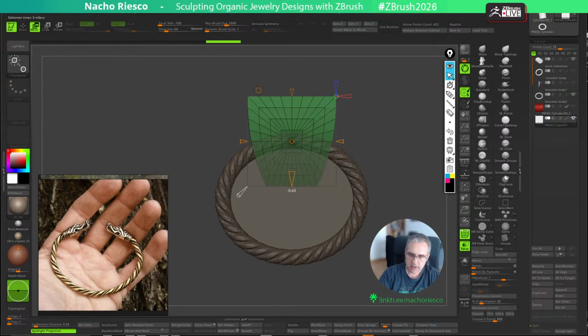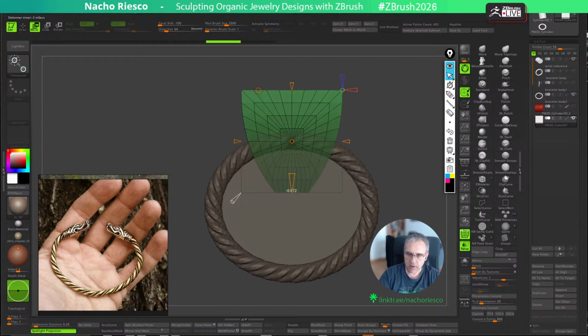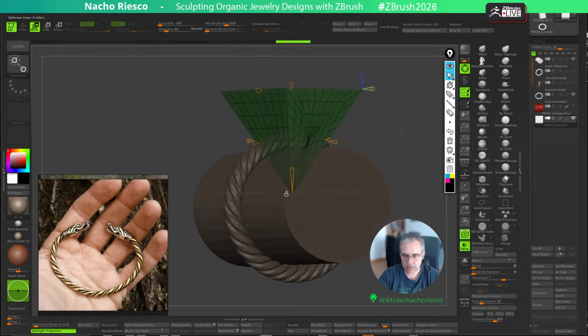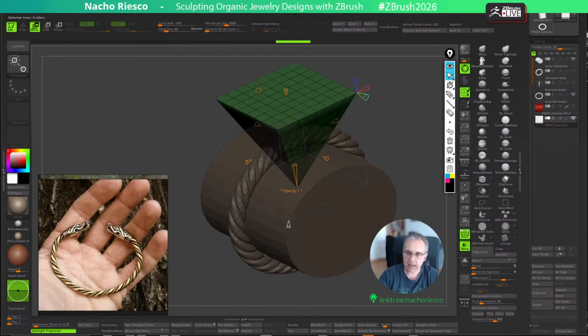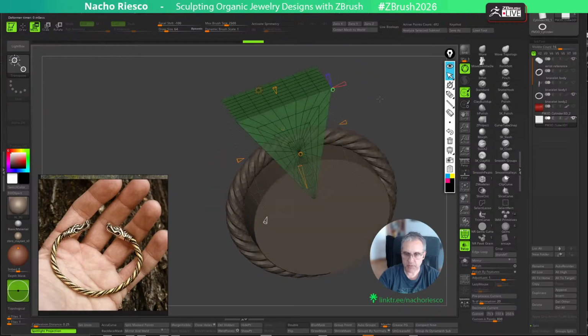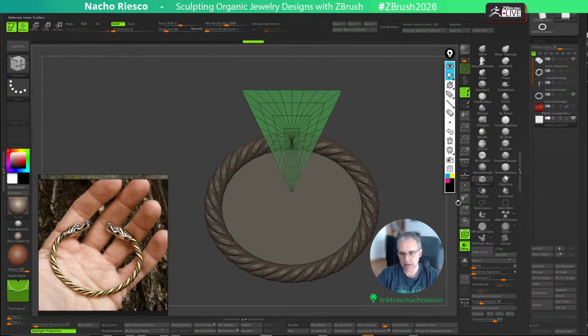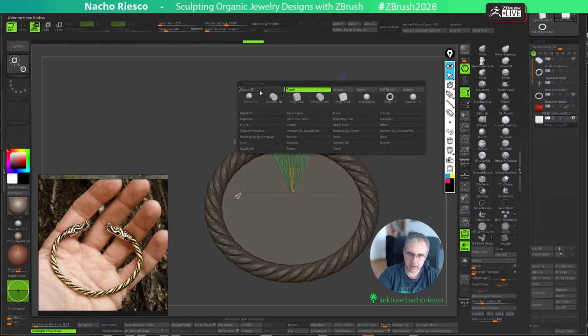For the tapering, you can see you can start making this, but if you are looking for a straight deformation, not with a curve as it is now, you should change the value of this cone from the minimum to 0, so you're going to be able to use this. And if you don't want to apply the deformation, in this case the tapering, to any of the axes, you can control that with this. You can remove this, and then it's gonna be like this. Maybe we can make it bigger.